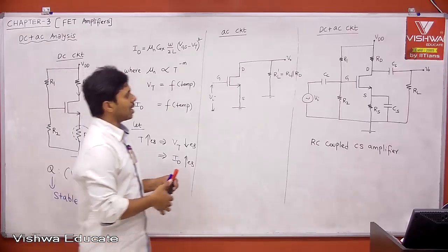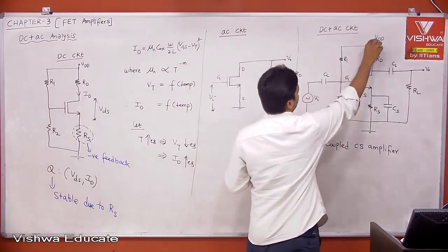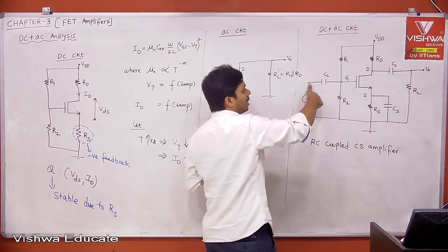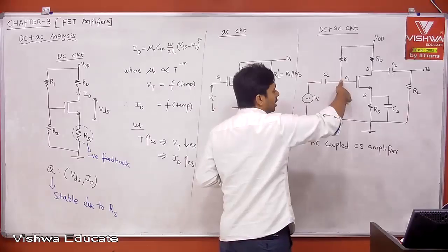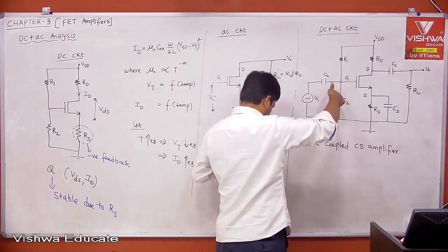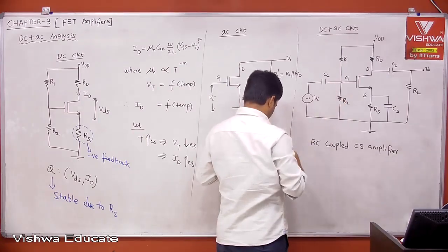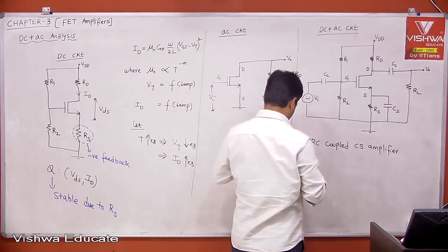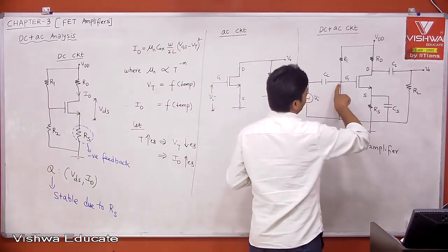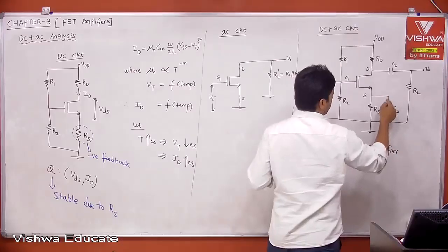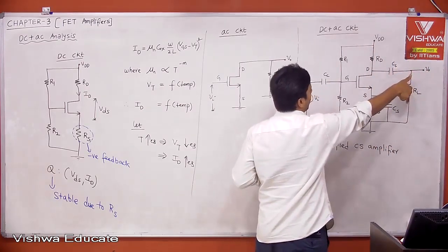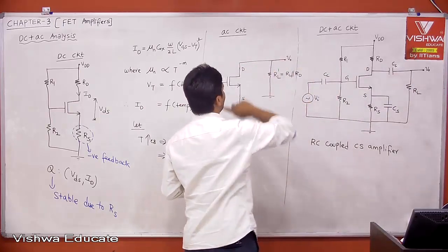Therefore, now if you see the AC analysis, short circuit, this is connected to ground, R1 is coming in parallel to R2, that is what is coming in parallel to your Vi. What is applied? Now, this is short circuit, source is connected to ground, then drain is connected to what? Output RL in parallel to RD, therefore it comes to the common source amplifier configuration.